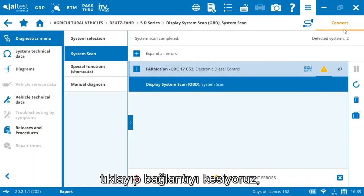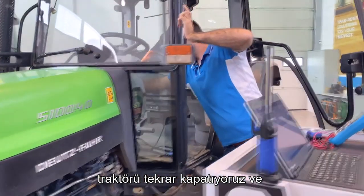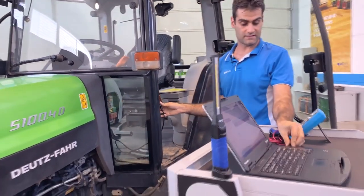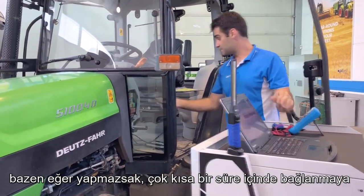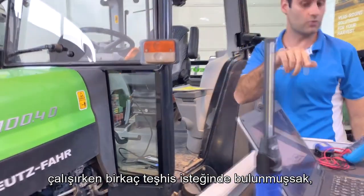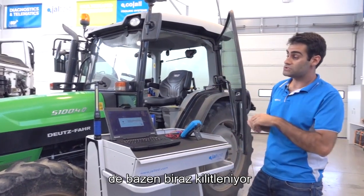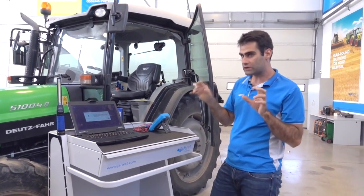Clicking on disconnect, switch off the tractor again and wait a couple of minutes. Also, I'm going to take the chance and reset the interface just in case. Sometimes it happens that if we have done several diagnosis requests trying to connect in a very short period of time, the electronic control unit also gets a little bit locked.